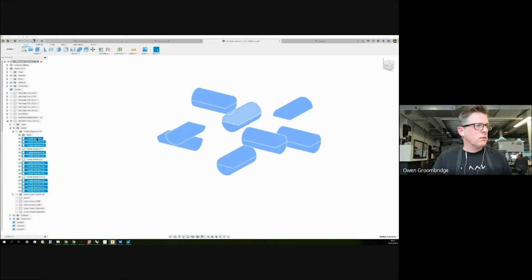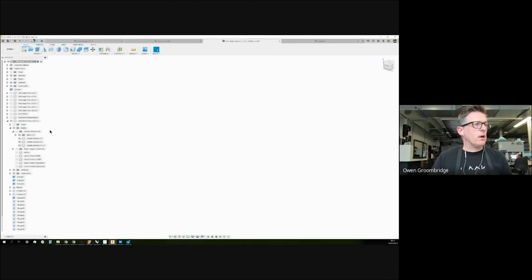While they're highlighted in blue, I right click on that and choose move to group. Sure enough, I've got those surface groups to move. You can move groups within groups within groups, which is very complicated. Then the target group is demo. Only select one target group, and then you go OK. Sure enough, demo contains those groups within it. That's how you do it.